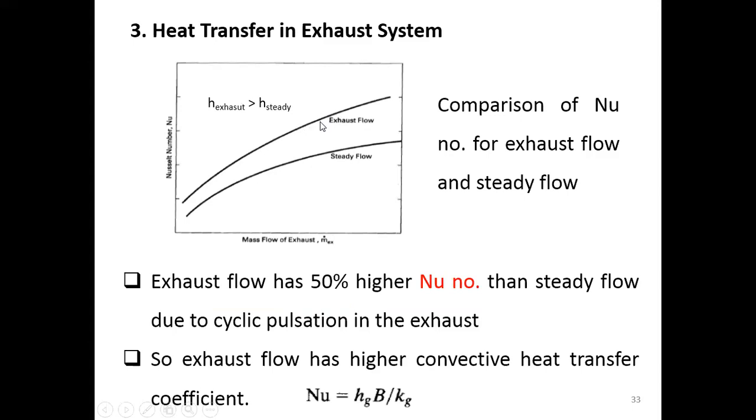It's not necessary, but according to this, it's about 50% higher when you compare these two lines together. I mean, is it just a matter of increasing the convective heat transfer, or is it also less conduction occurring? No, we're talking about the heat that transfers with the exhaust mass, because this is the exhaust system.